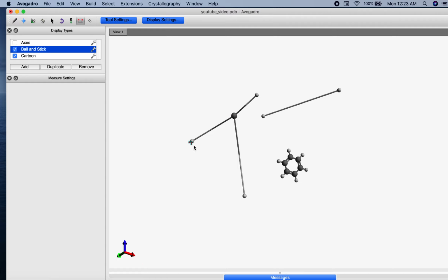Now I want to see the distance between this hydrogen and this. It's 13.266 Angstrom. Okay, so I want to see the angles between the three atoms. If you want to see the distance between the atoms, you need to select the two atoms. If you want to see the value of angles, then you need to select 3 atoms instead of 2. So here I just select 3. If I select 3, it will show you the angles. See, there is the angle, it's 73.9.